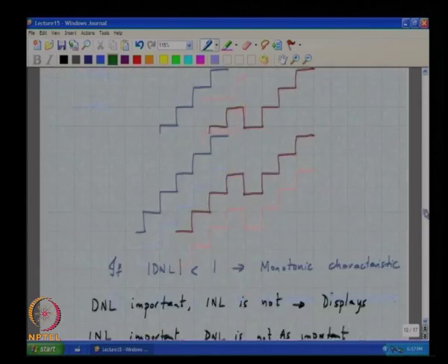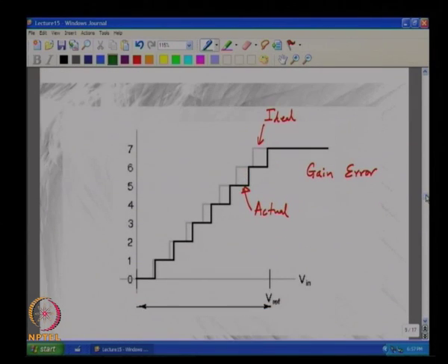Let us say our converter simply had a gain error, which as we saw is a benign thing. Now, if you simply define the INL as the deviation between the transitions for the ideal case versus the actual case, even though this converter is a pretty good one, you will see that the INL can become very, very large, simply because the slopes are different.